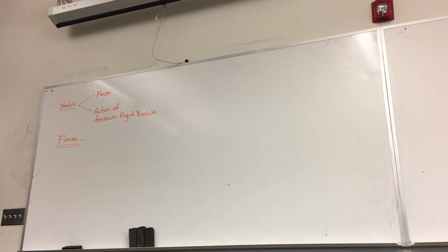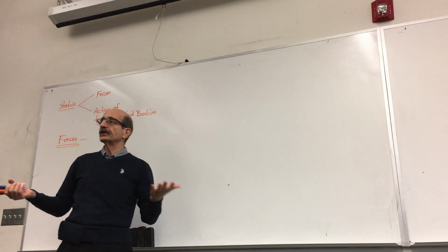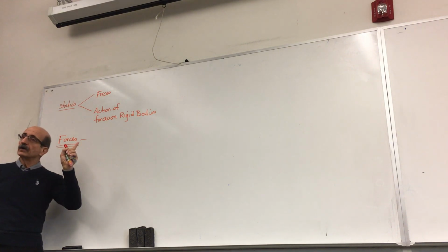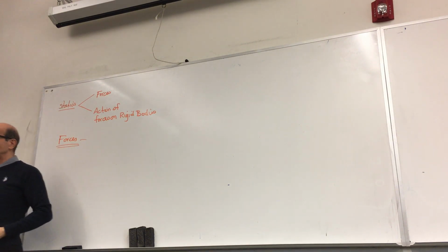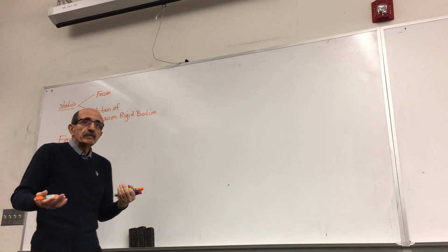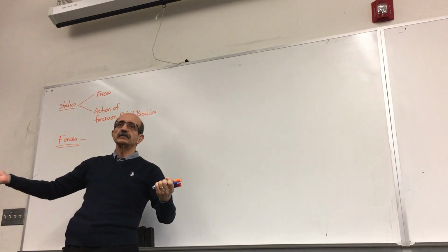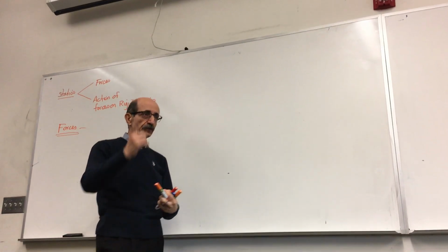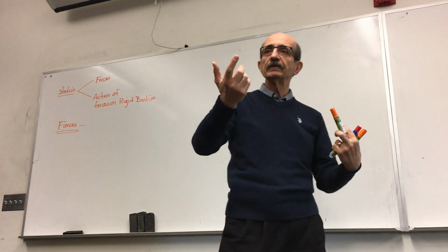We're talking about statics. So all objects, all particles that we consider in statics subjected to forces, stay in equilibrium, right? The concept of equivalent systems, if you want to interpret that, is what this basically teaches us: if you have tons of forces acting on a body, the action of all these forces is reduced to a single force and a single moment, right?